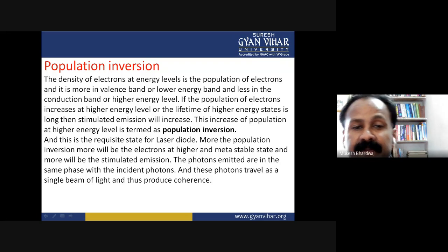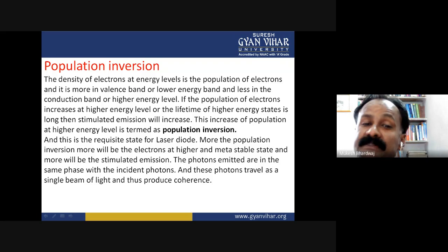On the other hand, a laser diode introduces two losses. The two main loss mechanisms are: many photons are absorbed within the semiconductor material before they can escape to create radiation. This is the major loss, or the first loss.